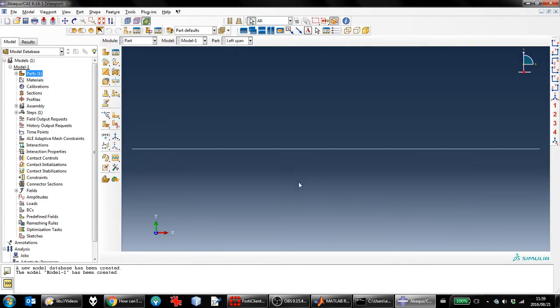The reason I defined one part for this is that at the rightmost end here we will have a hinge. Basically we need to define a second part for that infill span. Now this type of model could be modeled symmetrically if the loading is symmetrical. In this case I'm actually going to make the loading unsymmetrical. So we actually have to then duplicate this left span with its overhang end to be a right span with it.